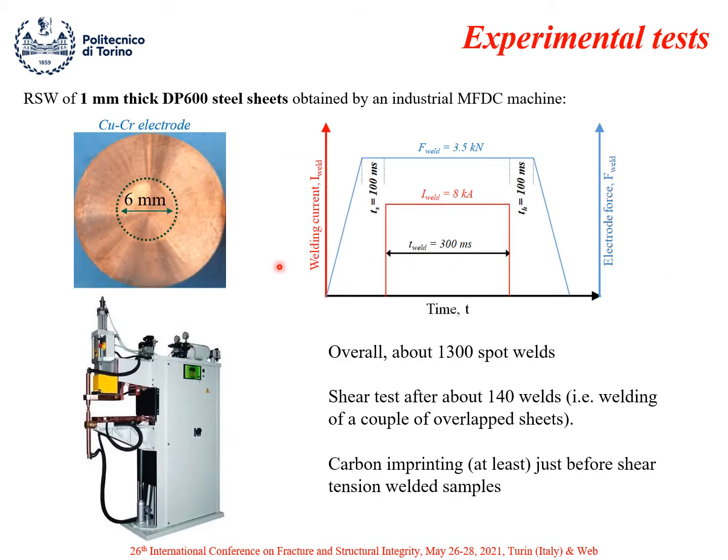We have carried out this activity on a dual phase steel with 1 millimeter of thickness through an industrial medium frequency direct current machine that you can see there. We employed some copper chromium electrodes with a tip face of 6 millimeter.